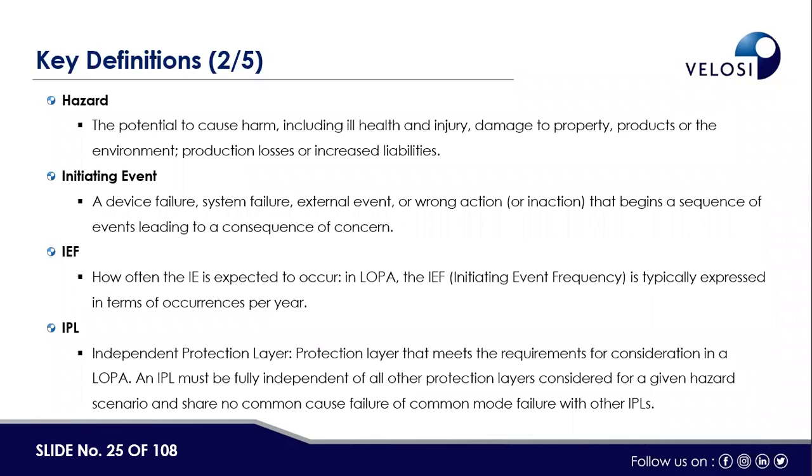Nowadays, in ADNOC, there are 7, structural integrity and life-saving, 2 more protective layers added. Whereas from a process plant point of view, there could be an alarm, a PSV, and a SIF. These are the 3 independent protective layers which may act during any abnormality in case of high pressure.